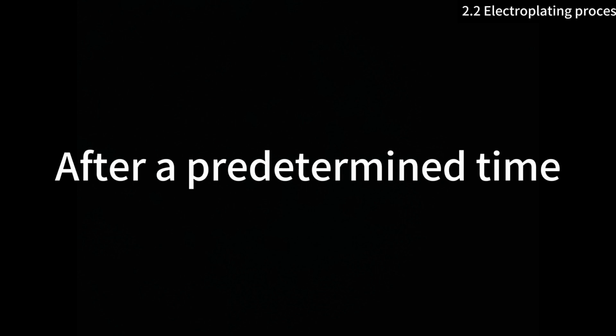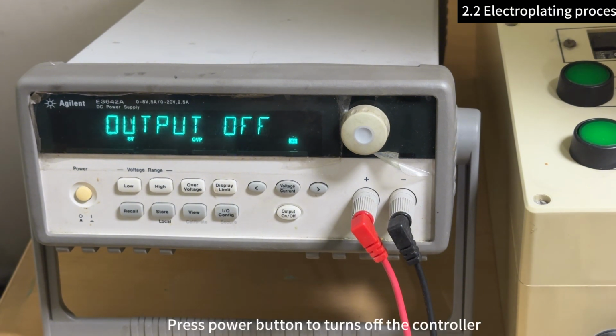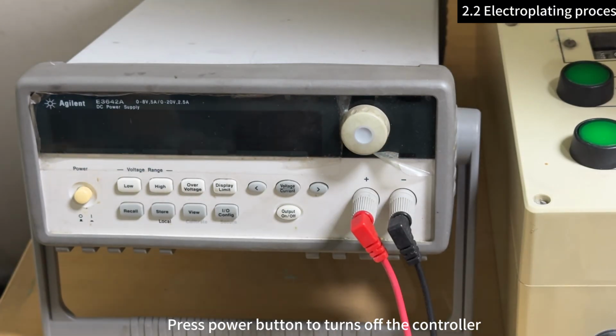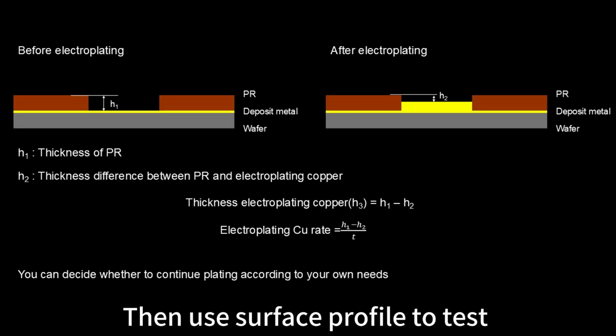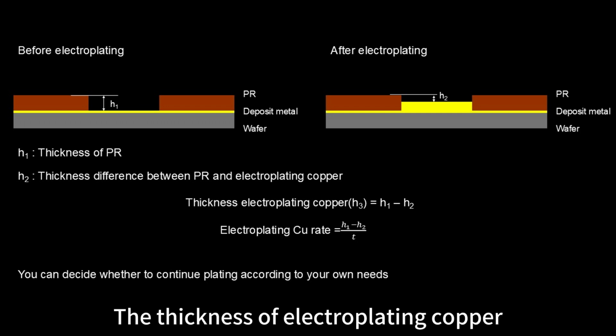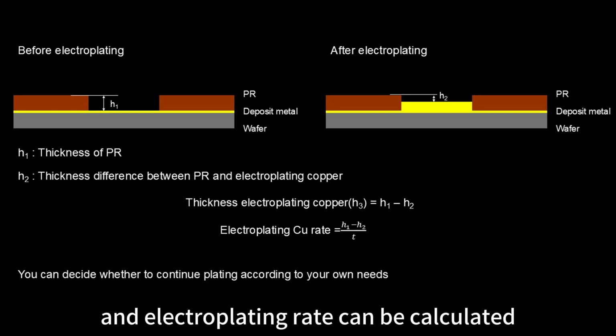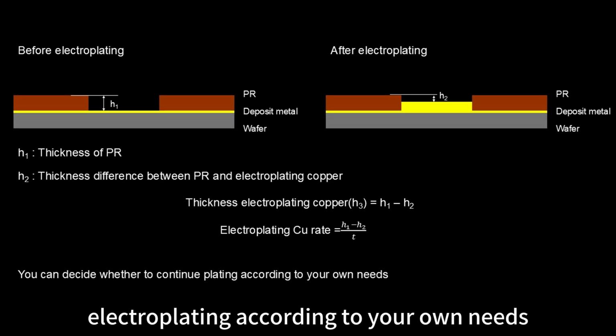After a predetermined time, press the Output button to stop the electroplating process. Press the Power button to turn off the controller. Then use the surface profiler to test the difference between the PR and the electroplated copper. The thickness of the electroplated copper and the electroplating rate can be calculated. You can decide whether to continue plating according to your own needs.